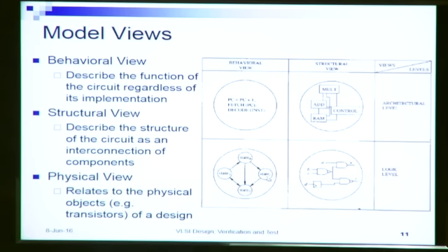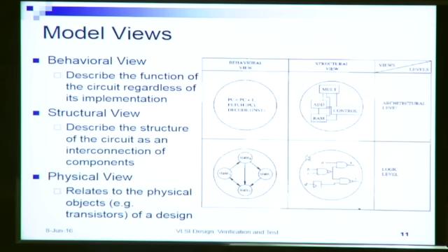At the logic level, on the other hand, we will have, let us say, a state machine corresponding to the controller that we have here. So the controller will basically control which operations should be executed at which time step, and hence this controller will essentially be represented in the form of a state machine. And that state machine again will be realized in terms of a gate level description, which will correspond to the structure. So the FSM here at the logic level will represent its behavioral view, and the corresponding structural view will be this gate level description.